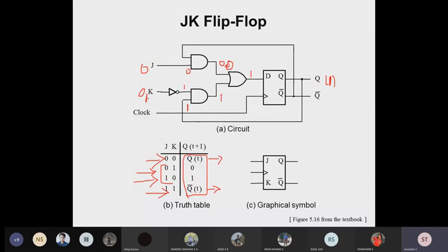So here 0 will get passed over for this AND gate. So this will result in 0. Now, since it's 1, you are going to transmit 1. Already, we have changed the K value as 1. So 1 and 1 will become 1 at this location. So 0 OR with 1 will result in 1.